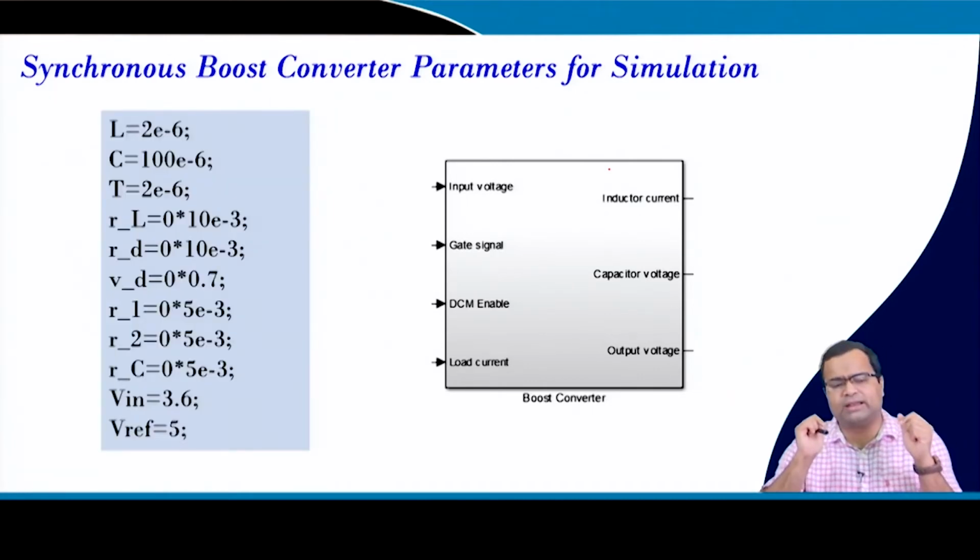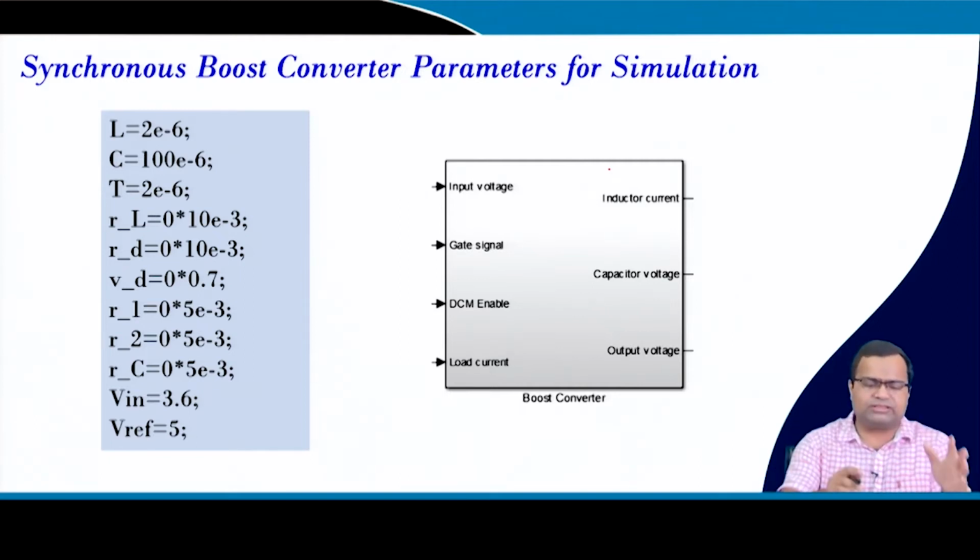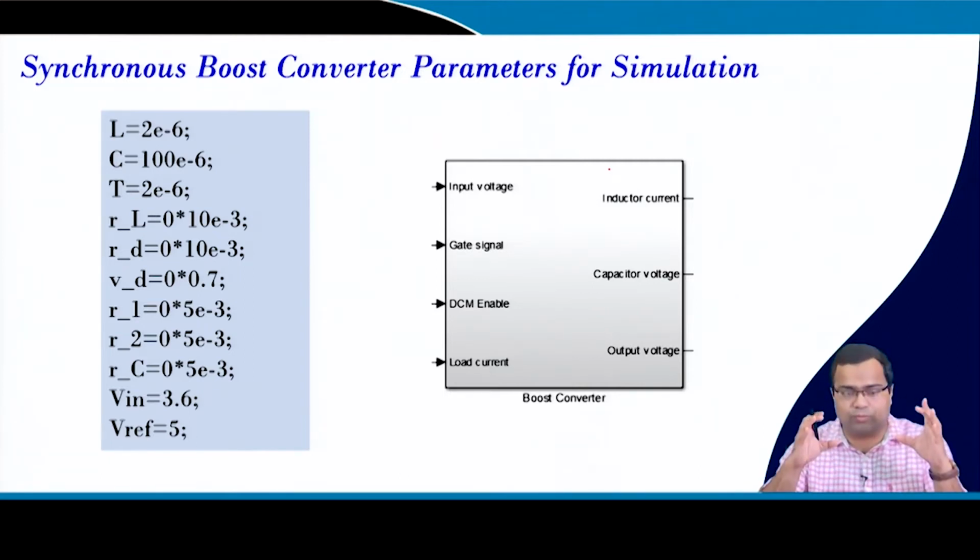For the boost converter case study, we have considered the LC values given here: a 2 microhenry inductor, a 100 microfarad capacitor, and a 500 kilohertz switching frequency.